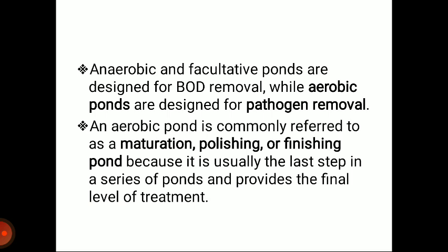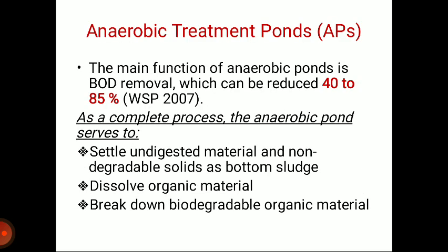Anaerobic and facultative ponds are designed for BOD removal, while aerobic ponds are designed for pathogen removal. An aerobic pond is commonly referred to as a maturation, polishing, or finishing pond because it is usually the last step in a series of ponds and provides the final level of treatment. Anaerobic treatment ponds, that is called APs.